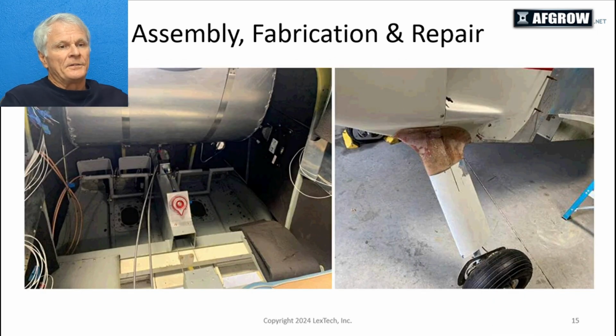Now, you can see on the left the fuel valve. The original fuel valve was at the bottom of the tank, which is impossible to reach when you're sitting in the airplane and flying. So I really wanted to bring that forward, so I brought it forward. As a result, though, it then required me to use an electric fuel pump because gravity feed didn't allow enough pressure because of the losses involved in taking that extra route to that fuel valve. But I think it was worth it, at least I could reach that valve in flight if I ever had to.